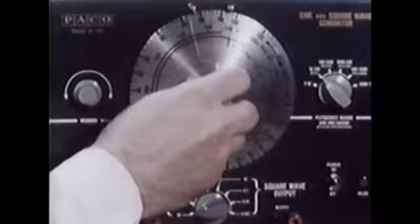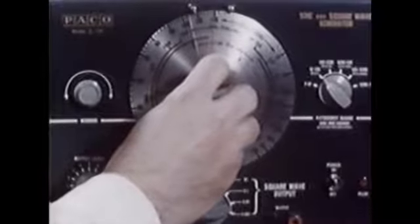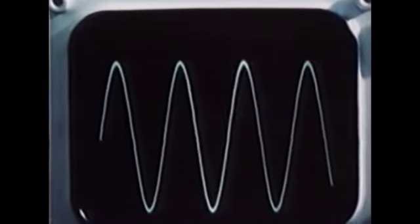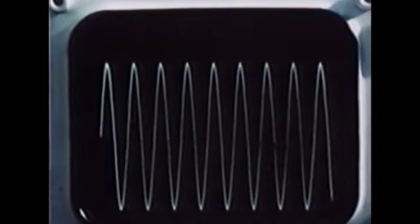The oscilloscope can help us see different frequencies. It represents a 60-cycle wave on the screen by one cycle of the sine wave. If we double the alternating current's frequency to 120 cycles per second, 2 cycles are displayed in the same time interval. As we continue to alter the frequency, the oscilloscope allows us to observe this change.